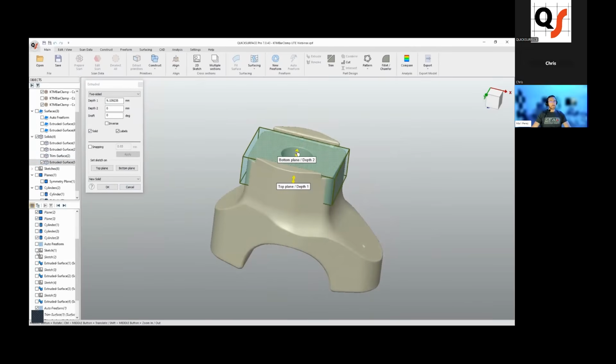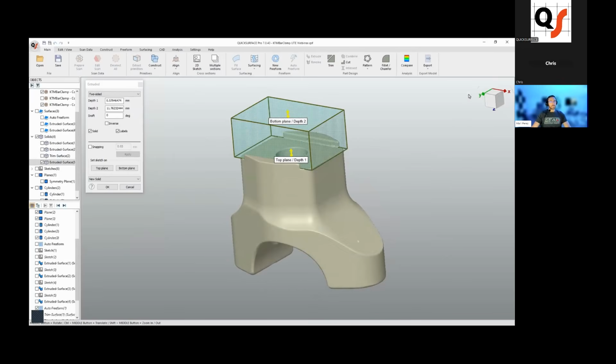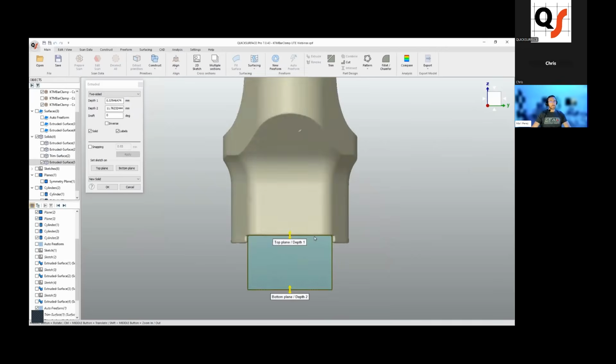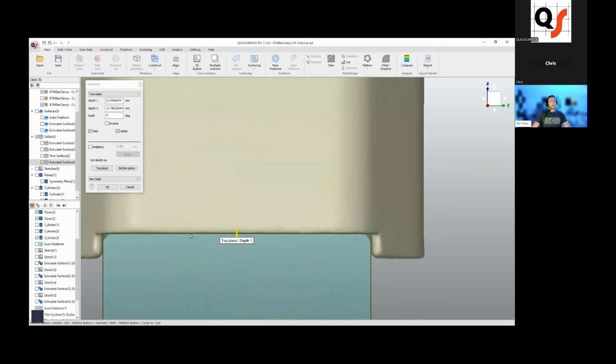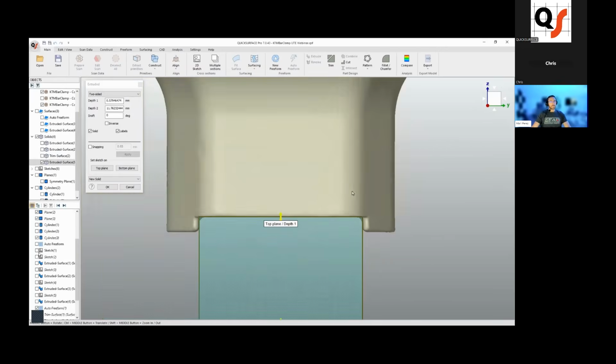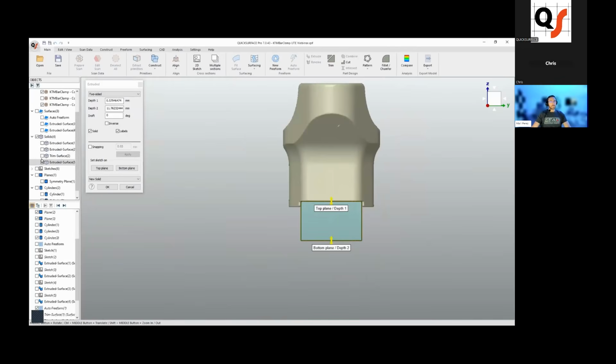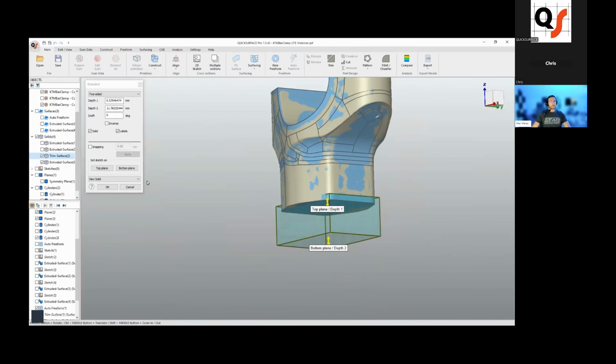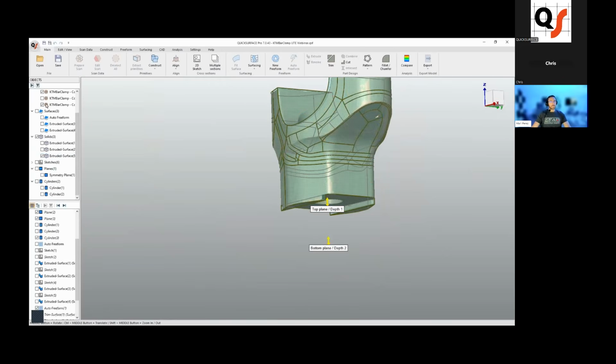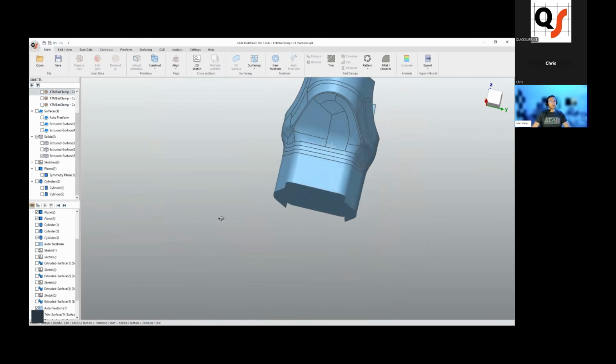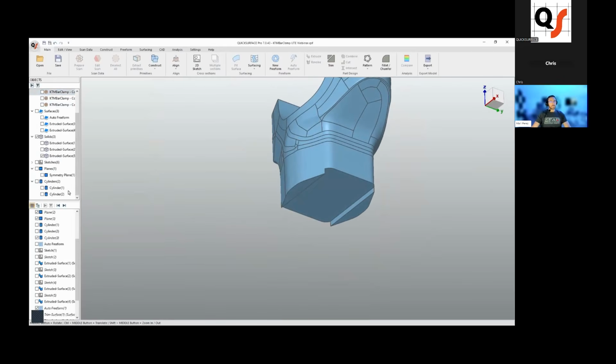From here, if we pull this up, what this actually gives us the ability to do is hold down Control and snap to that face. So we didn't have that option when we were doing this in Lite, and now we can snap directly to that face. If I show my solid, in this case it's trim solid, I can use it directly as a cut tool and go right in and remove that material. So if I hide the meshes, you can see that we were now able to cut that piece away.